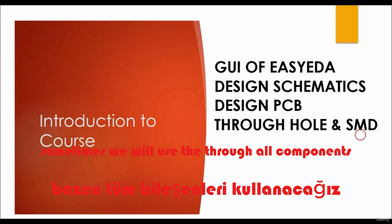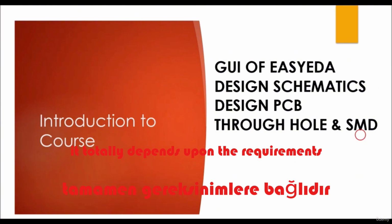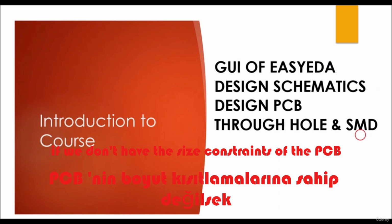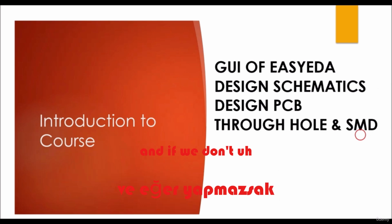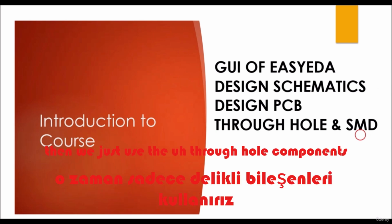Sometimes we will use the through-hole components and sometimes we will use the SMD components. It totally depends upon the requirements. If we don't have size constraints for the PCB, and if we don't need to worry about the fitment of the PCB in the mechanical design, then we just use the through-hole components.